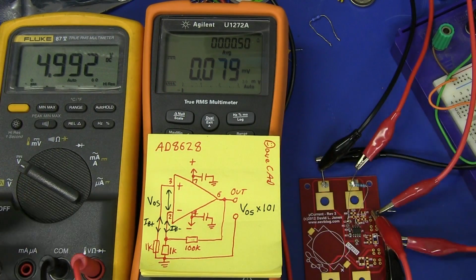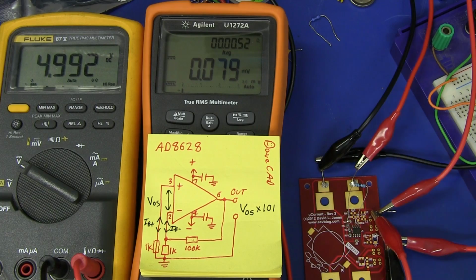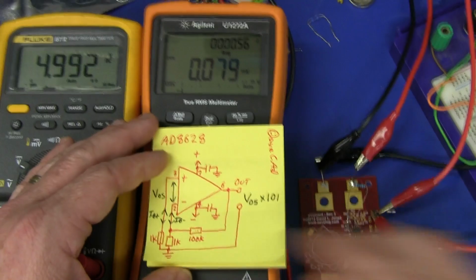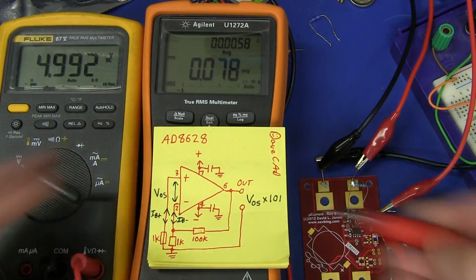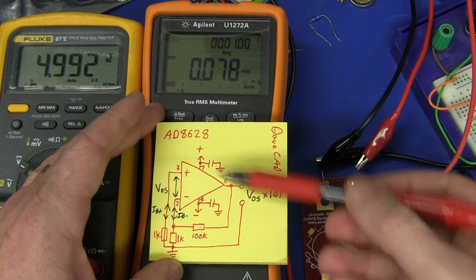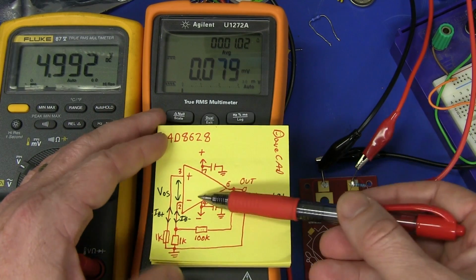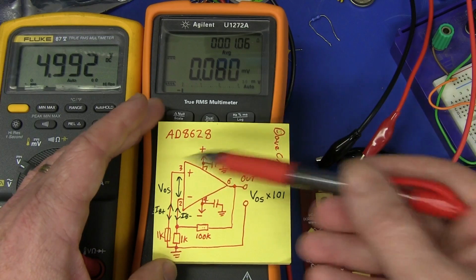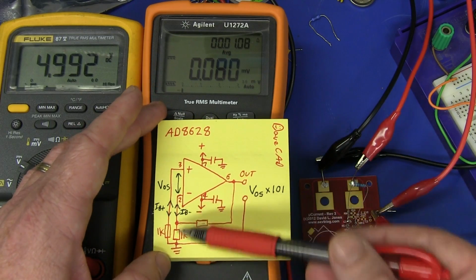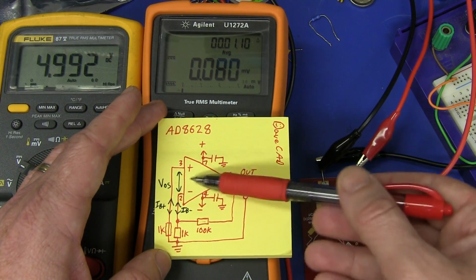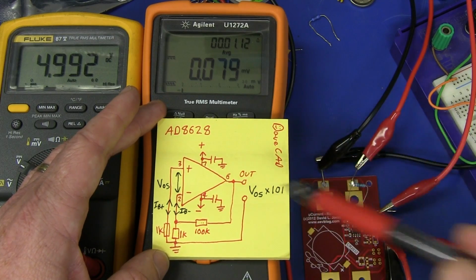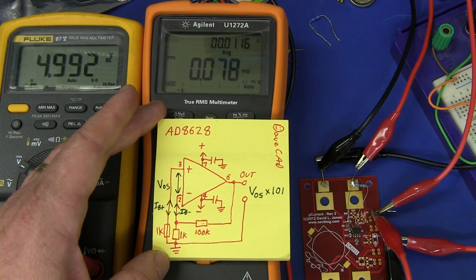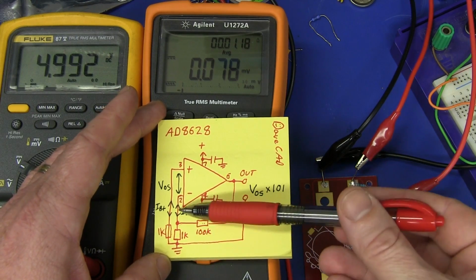We've trimmed this thing down so it's better, but we don't actually know what the exact culprit was, because this is a rail-to-rail op-amp, so we don't exactly know the topology. Add on that this is a chopper amp as well, so there's going to be input switching current and all sorts of stuff to do with that. And this isn't just your regular op-amp, by the way. I've done a whole video on chopper amps, which I'll link down below, as I did on the previous video.